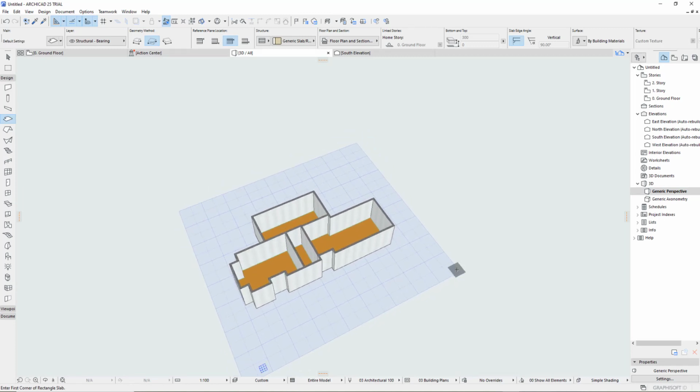So that's the basic workflow from scanning a space, uploading it to mymatterport.com, letting it process, downloading your Matterpak, importing your XYZ file into ArchiCAD, setting up your slice in the settings of the GDL object, and then using the tools within ArchiCAD to trace over the point cloud.